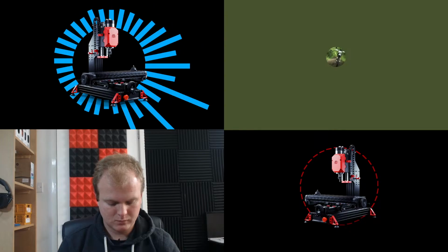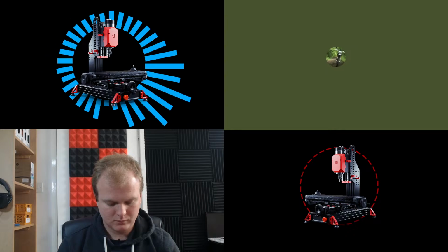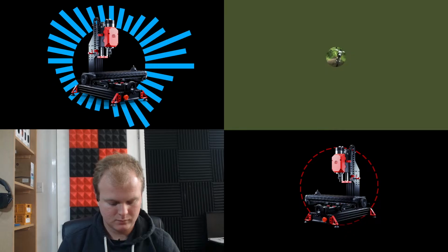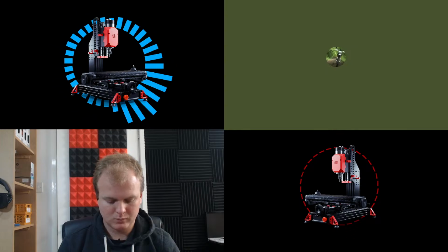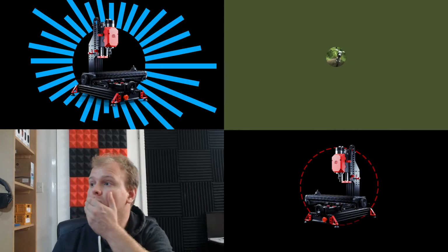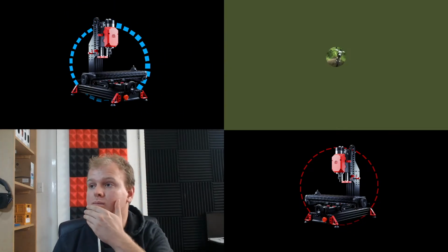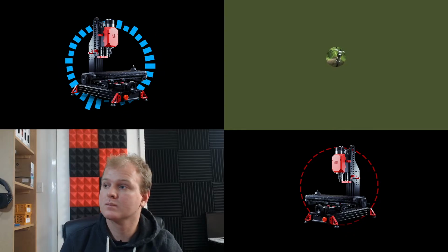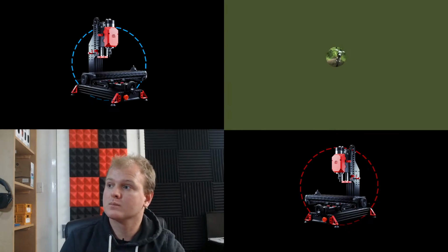And what that means is that we can make basic user inputs control some pretty complex probing methodologies to get people started with RepRap firmware for machining, even if they have very little experience in actual machining tasks. So Millennium OS as a thing is a package that's installed into RepRap firmware, with a post-processor for Fusion 360 that creates G-code for RepRap firmware.